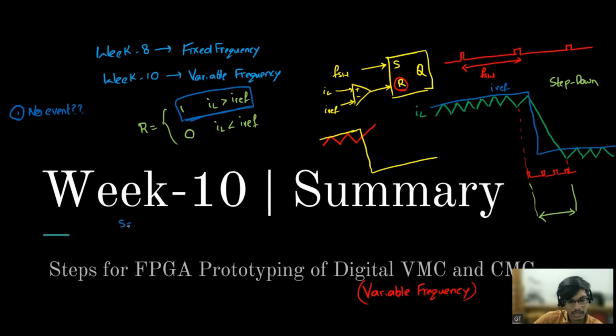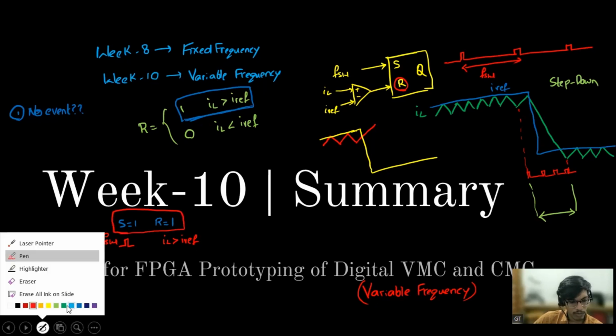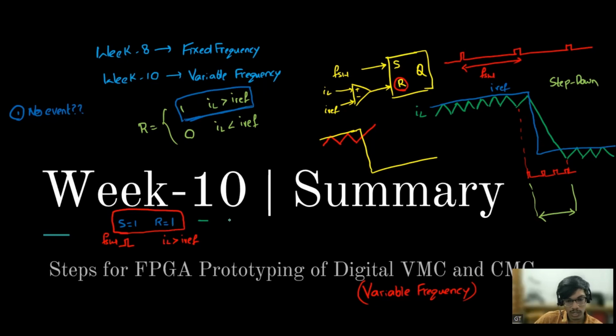Say S is equal to 1, R is equal to 1, which means there has been a switching pulse, an FSW pulse has come. Also, IL is greater than I reference. But I know that when IL is greater than I reference, irrespective of the switching pulse, it should be turned off so that IL will fall down and go below I reference. Which means when both set and reset are 1, based on the logic, so that the system will not collapse, I know that it should be reset, which means it is again reset dominated. This part is clear?